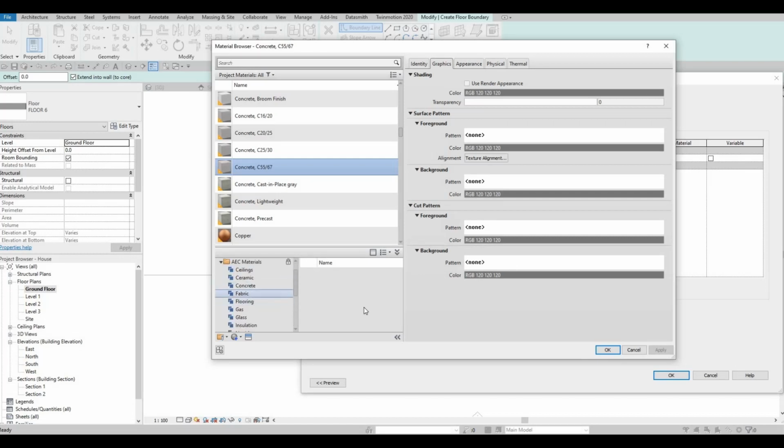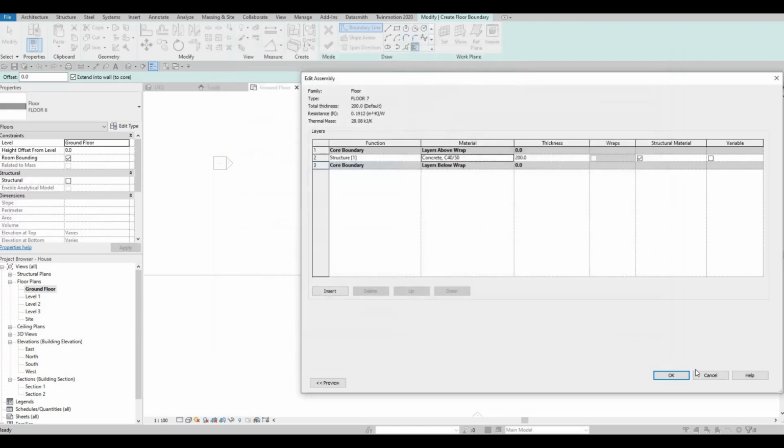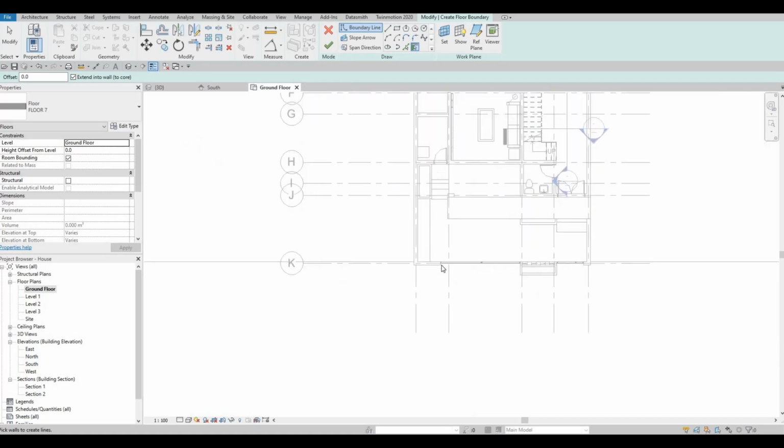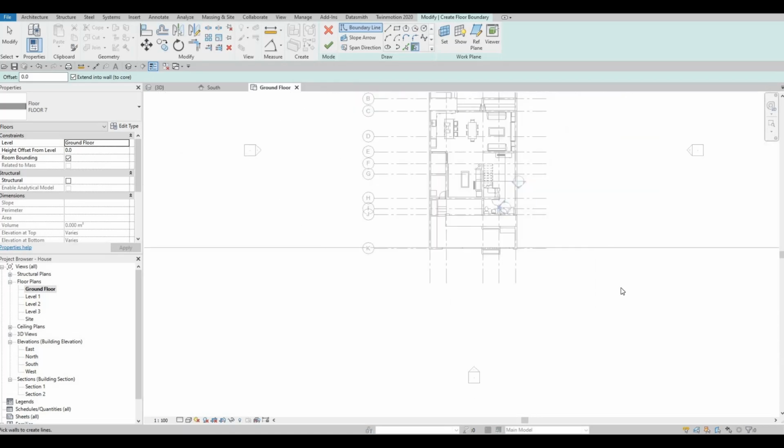The reason that I'm changing different materials all over is because I want the ability to change this. So if I am given a chance to change it, I don't need to go back and forth into my Revit to change the material, but I just need to change it in Twinmotion. So that's why I keep on changing stuff.